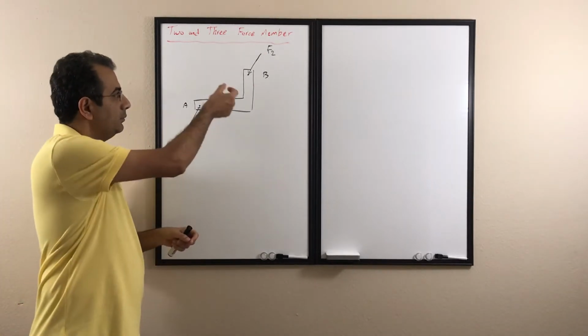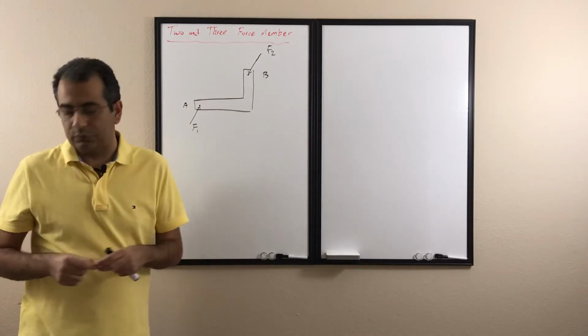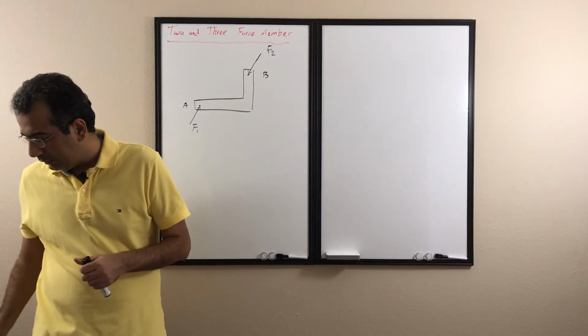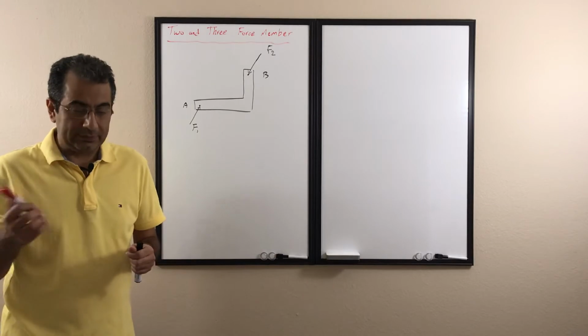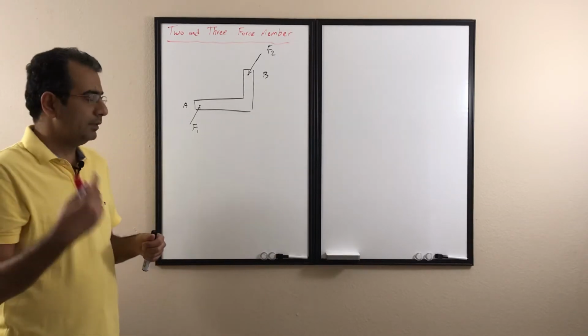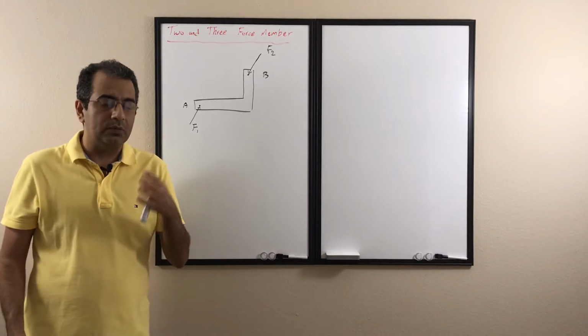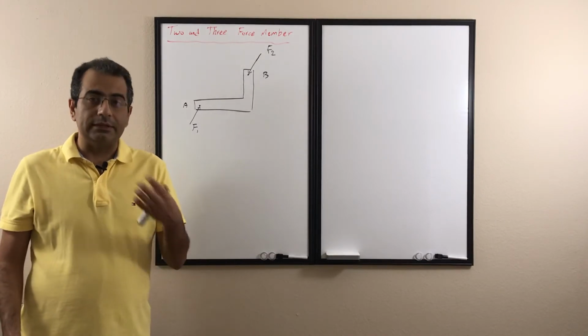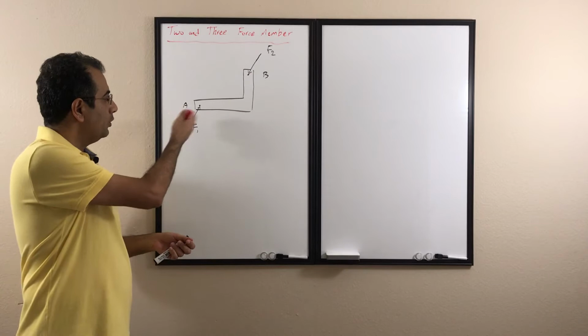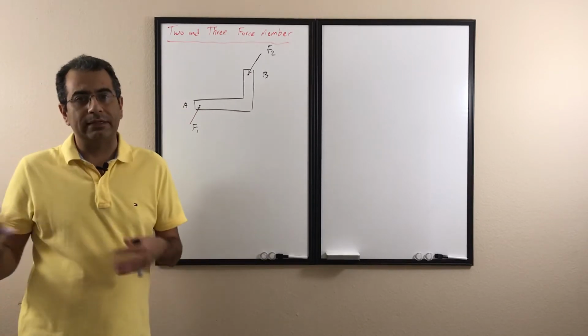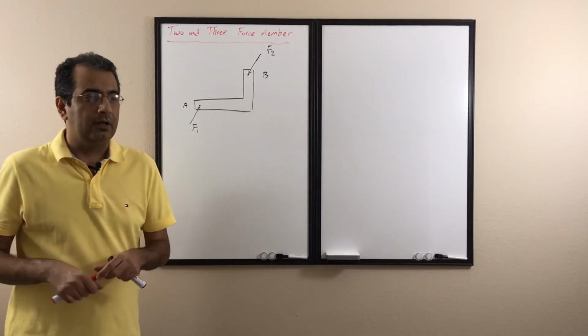So it's a single element with 2 points and there are 2 forces applied on that. One thing I want to mention, remember that every time we were dealing with 2D problems, before we start to do anything, in most cases it's easier to find the components of all forces in the x and y direction before I start solving it.